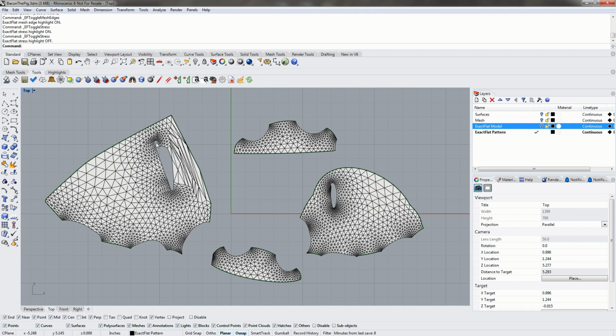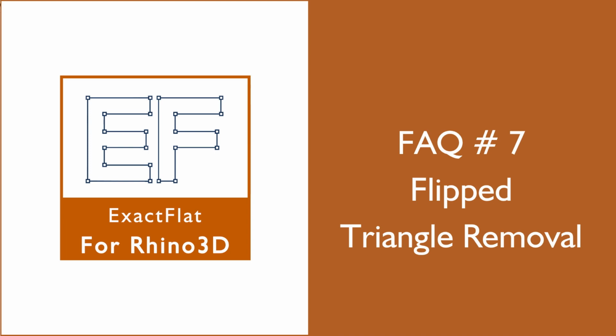And lastly, the third method is to do manual vertex manipulation, and this allows you to manually drag vertices of triangles to change the orientation of the triangle. And you can use a combination of all these three methods with the divide and conquer by subdividing your mesh to make it easier to use some of these tools. And again, this helps with preserving the shape of the pattern.